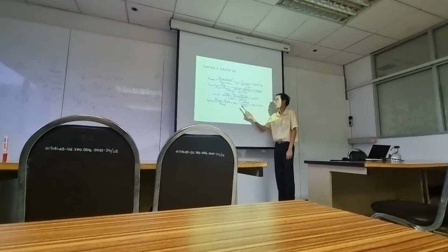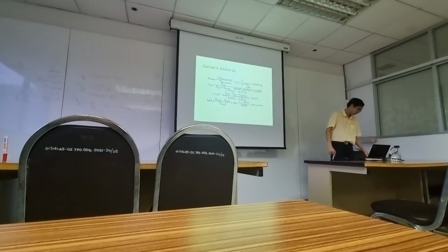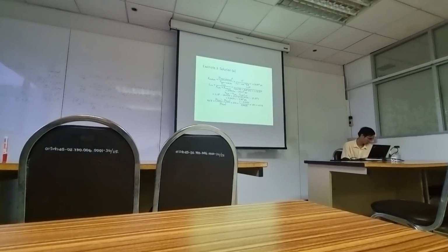Then if you want to find the voltage regulation, you have 1 minus 0.9433 divided by 0.9433, you have 6%. Okay, any question?